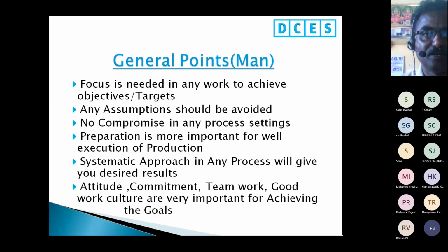The calculation will help us 80%, and 20% has to be validated properly. And no compromise on any process settings. For example, when we see any leakages in the machine, any water leakages or air leakages, they should be arrested. Otherwise, we will not get consistency in the process.